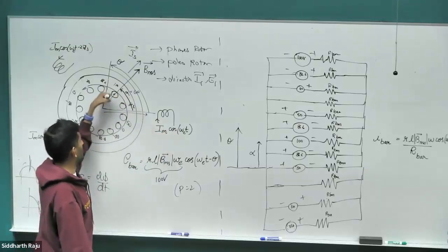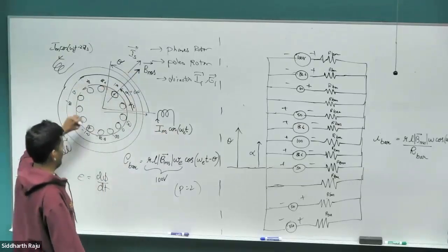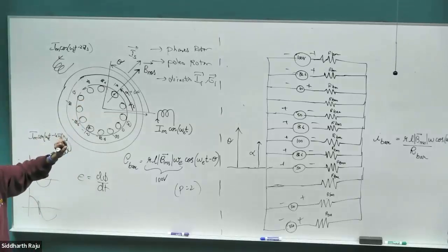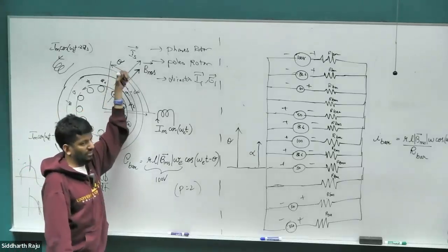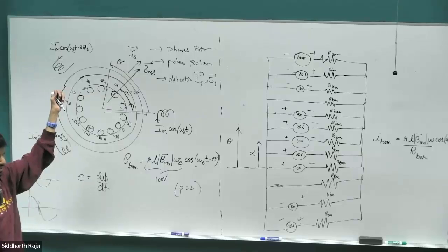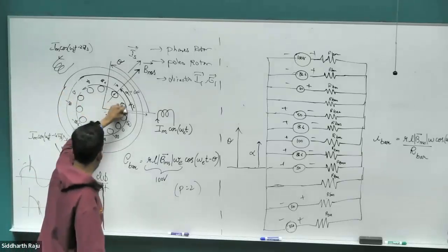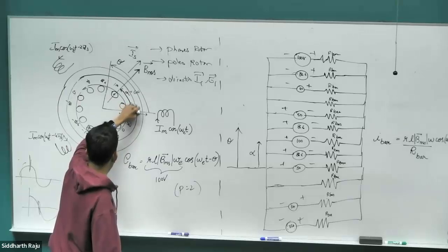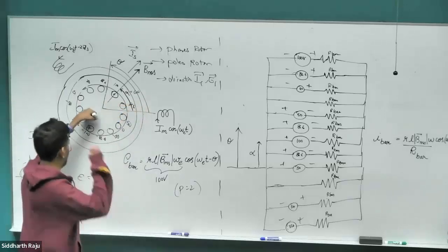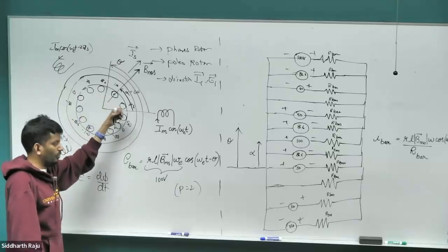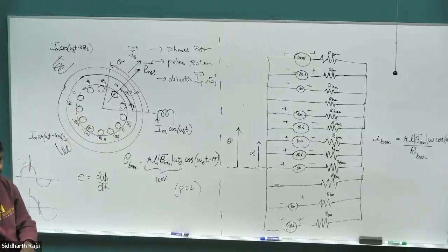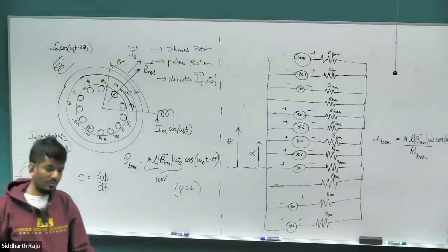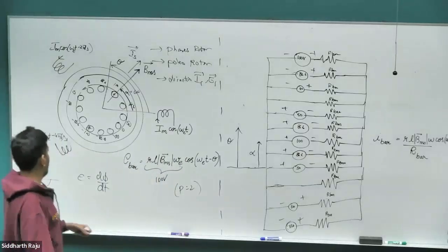So even in this case, when I have the EMF space vector here, the B field due to every single phase was the original real-valued function. But once we put it through a space vector transformation, you will get it to point along the direction where the net B field maxima would be. So going back to this question, it has nothing to do with whether your currents are real or, of course, there is no meaning to having negative imaginary currents, but the space vector is not directly relating to the actual currents themselves in the sense of the actual phase values. Okay? Where would be the rotor current space vector? Lagging by delta. What was it? Lagging by delta. What is delta?